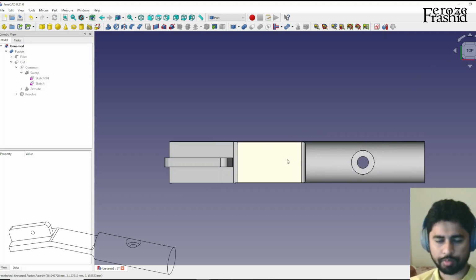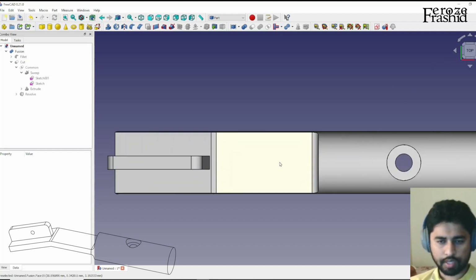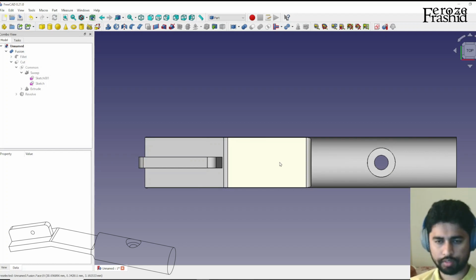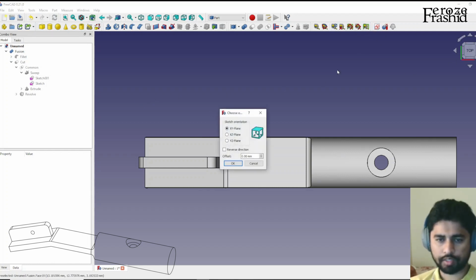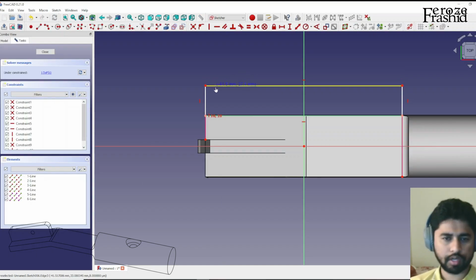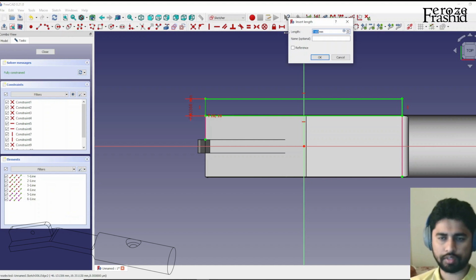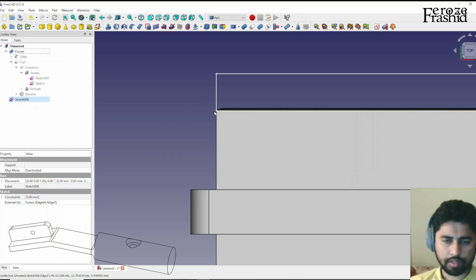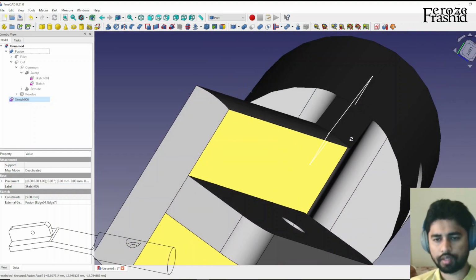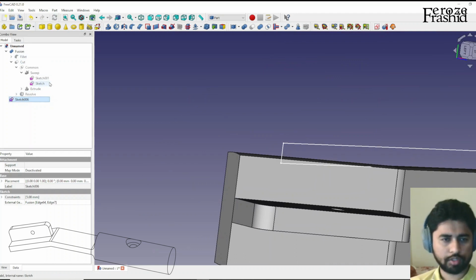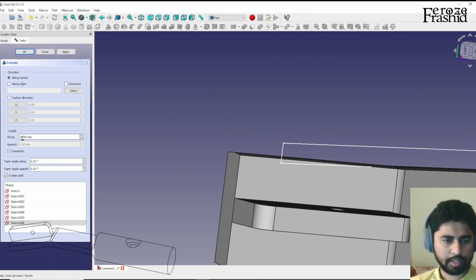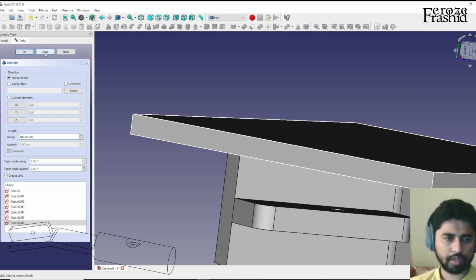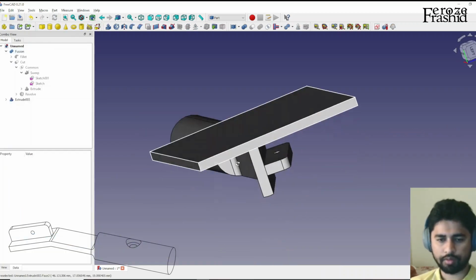Let's come up to the top, and I want to make another common. On the top I want to make another sketch on the XY plane. This height, I'm going to say this is 5. So that's our profile, right? I want to make it symmetric, say make it 100. Apply, close. Does it cover the whole thing?